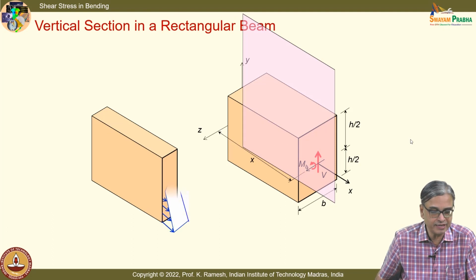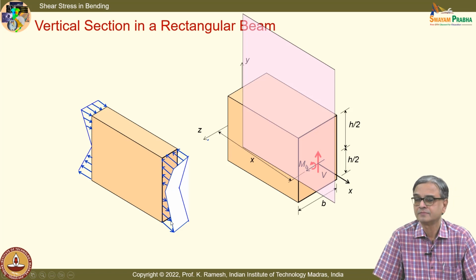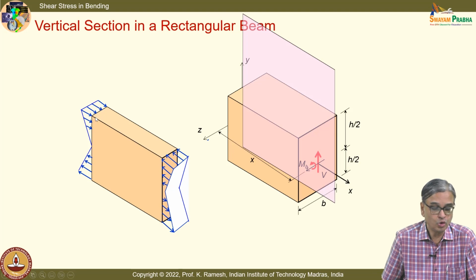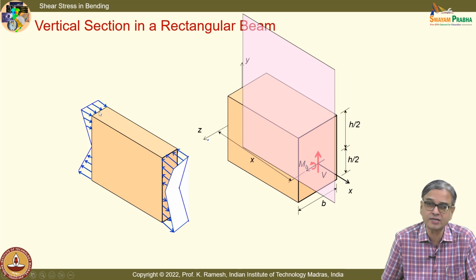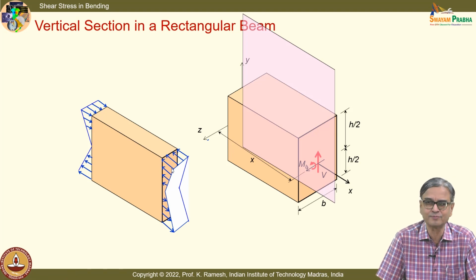and bending moment varies along the length of the beam. So, I will have bending stress variation like this on this surface and bending stress variation like this on this surface. And you know very well, when I substitute the bending moment, which was smaller in magnitude here, I will get smaller stresses, I will get larger stresses on this face. I mean, this is difficult to draw. I have drawn it to the extent possible. If you can improve the figure further, you are welcome to do so.